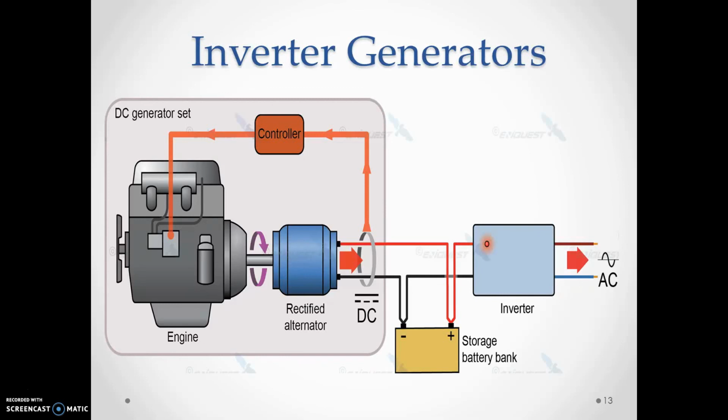It directly or indirectly reduces losses. When the drop of a load is significant, it can maintain the lowest possible speed necessary to meet the demand without shutting off and restarting the generator as the load increases. This is cost effective, reducing losses, and efficient, because if you are shutting it off and restarting it, you are consuming more fuel and wasting more energy.